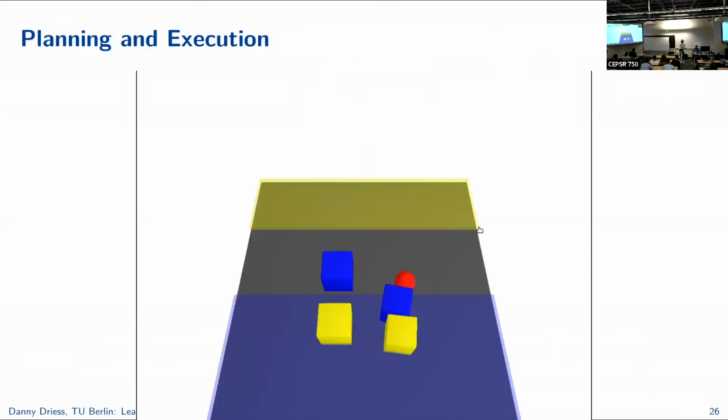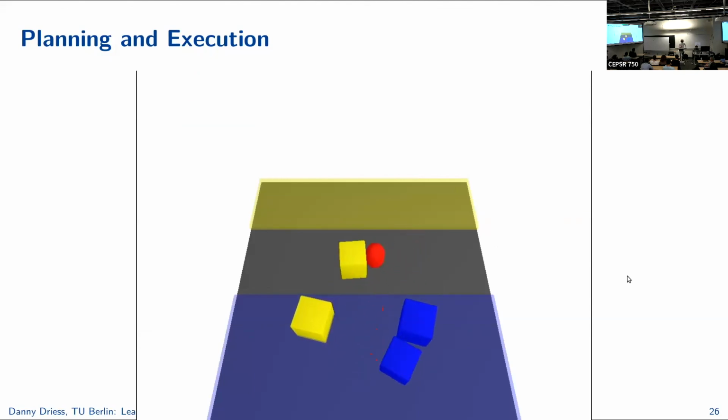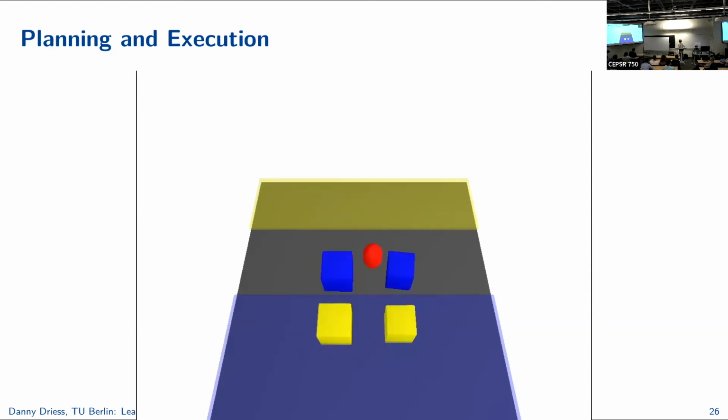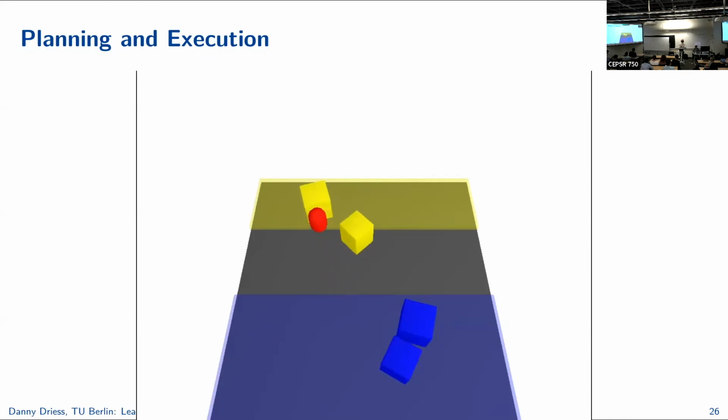Okay, and I think for the interest, 1 minute maybe. We then also used this model to do planning and control. So this is an object rearrangement task. Maybe this task doesn't look challenging, but it is actually challenging if you have a learned dynamics model, because it's necessary to plan. It's not possible to do greedy planning here. If you do greedy planning, you might undo something, or you never achieve the goal. So you need a dynamics model that's capable of predicting long into the future without a lot of drift.